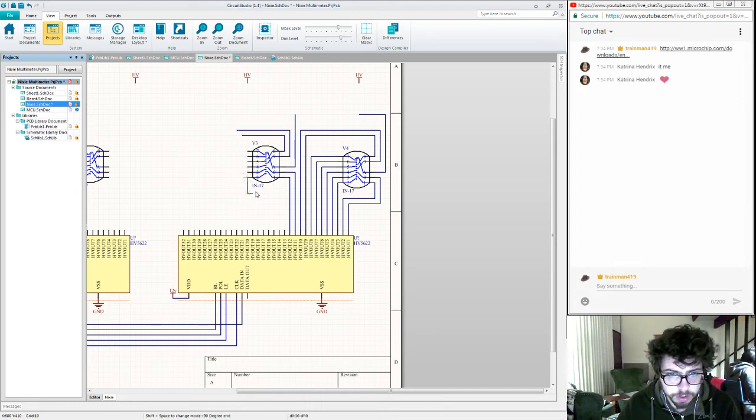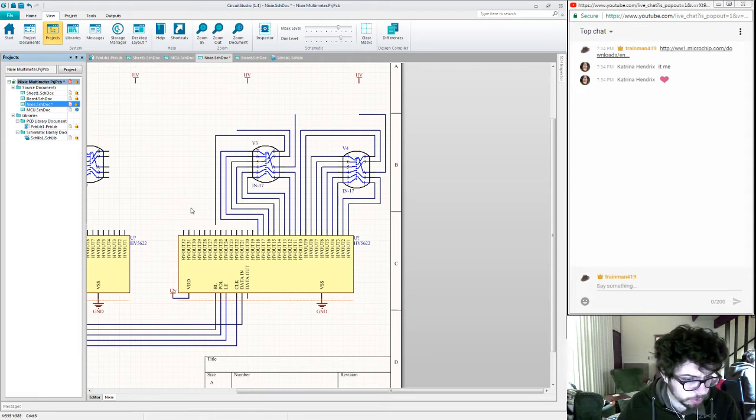So I can run those around the top and immediately run into the same problem I ran into before, where I have to zigzag these across the bottom to get the schematic to look reasonable at all. I think the only appropriate way to do this is to reduce my grid size on my schematic and pack them in tighter here. Make sure that that's still readable.